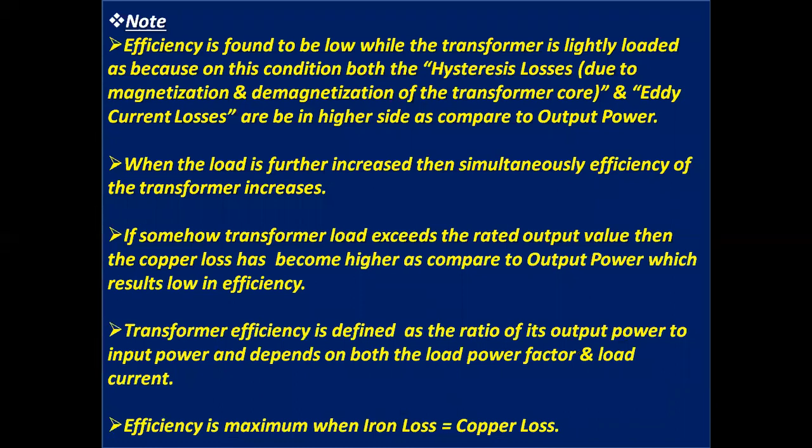Note, efficiency is found to be low while the transformer is lightly loaded, because in this condition both the hysteresis losses due to magnetization and demagnetization of the transformer core and the eddy current losses are on the higher side as compared to output power.